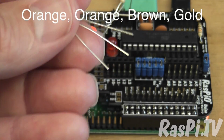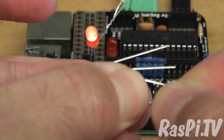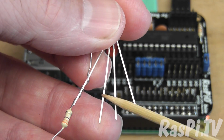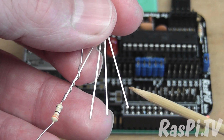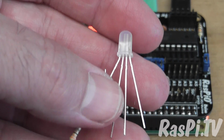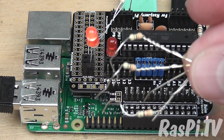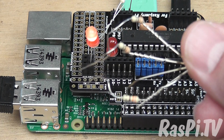and we're going to wrap them around like we did with the single LED and connect it to each of the color legs, not the ground leg, but this one and this one. There's a photograph on page 34 of the manual in case you're in any doubt. And what you'll end up with is something that looks a bit like this. Okay, I've bent these so that they're in the right order.